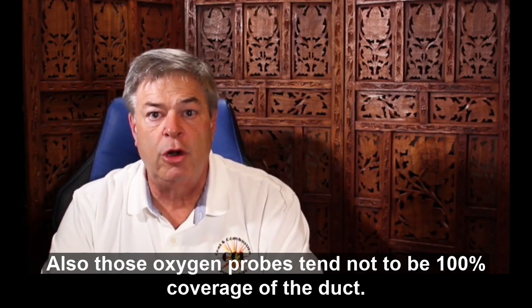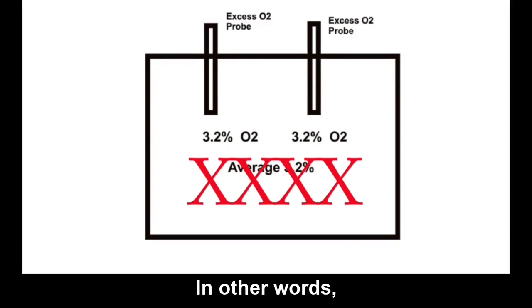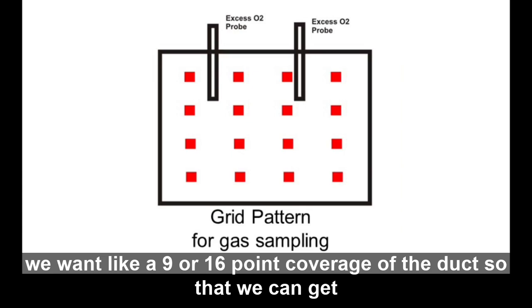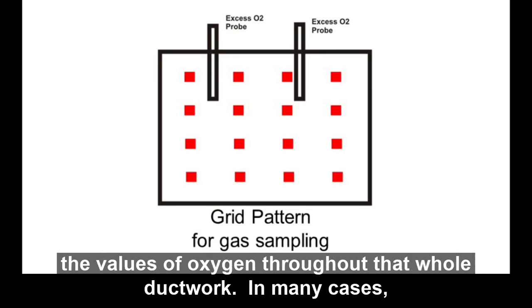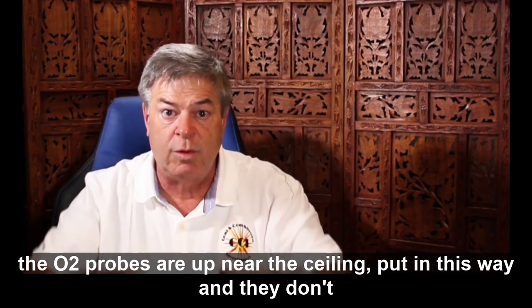Also, those oxygen probes tend not to be 100% coverage of the duct. In other words, we want like a 9 or 16 point coverage of the duct so that we can get the values of oxygen throughout that whole ductwork.